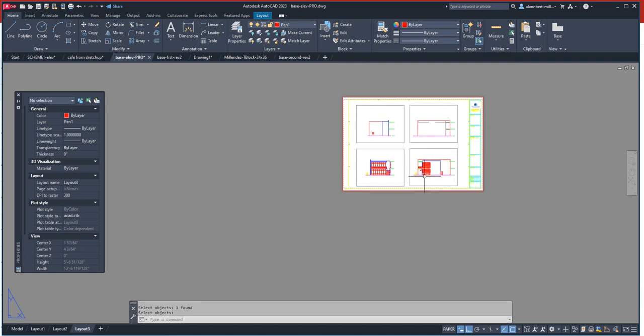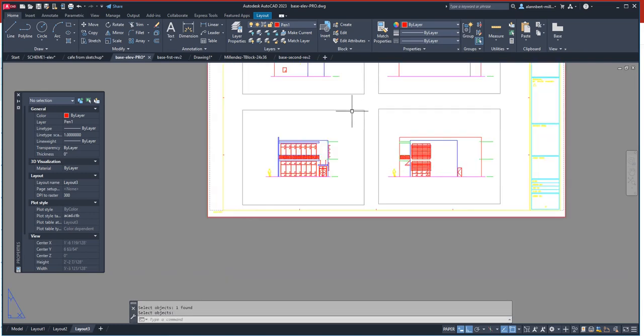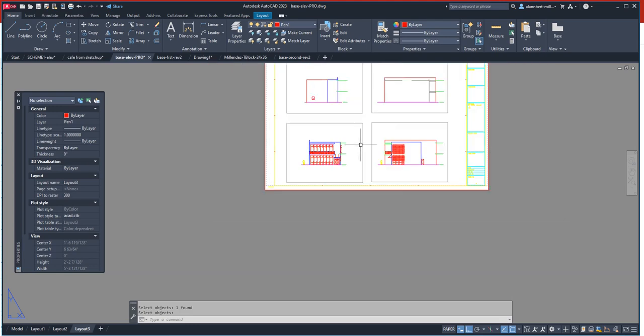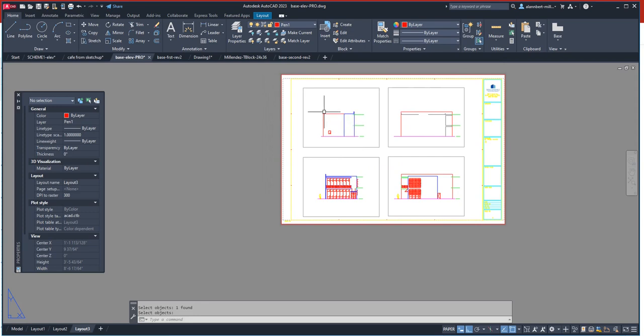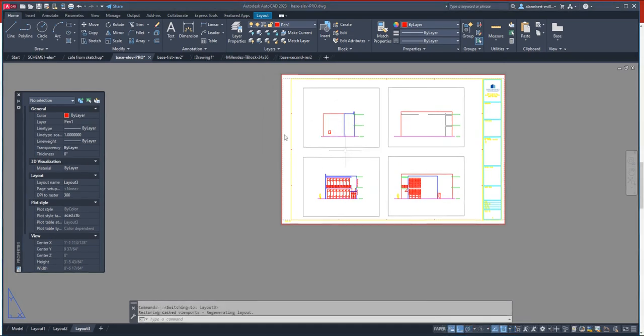There you go. Okay, so once you hit the viewport, you can't move them again. You also want to line them up, but we don't have any grid markers yet on the elevation, so we're going to do that next. Let's go ahead and select a floor plan to put in some grid markers.